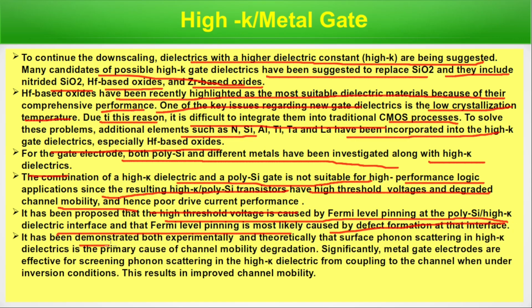It has been demonstrated both experimentally and theoretically that surface phonon scattering in high-K dielectric is the primary cause of channel mobility degradation. Significantly, metal gate electrodes are effective for screening phonon scattering in the high-K dielectric from coupling to the channel when under inversion condition. This results in improved channel mobility.